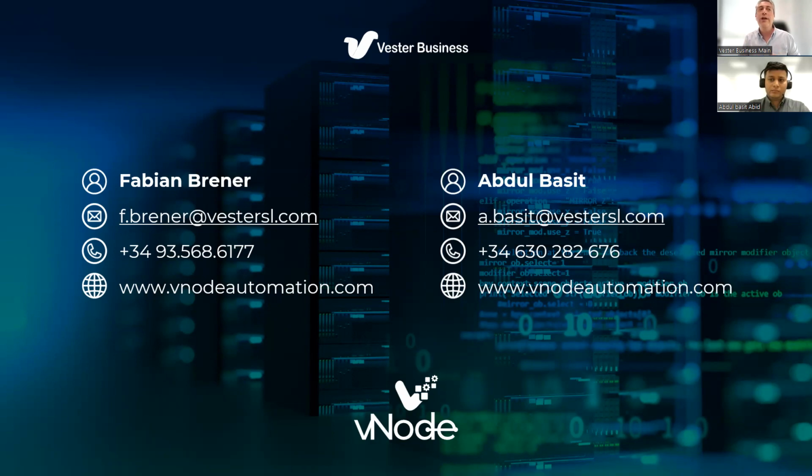But what you do want is to collect the data from your control devices every second, send everything to your IoT gateway, and then using this real-time data, make all your calculations: average every 10 seconds, average every minute, the max value every hour, or the addition of 2 or 3 or 4 tags or any kind of crazy calculation. And the result of that is what you want to send to AWS with just one connection.